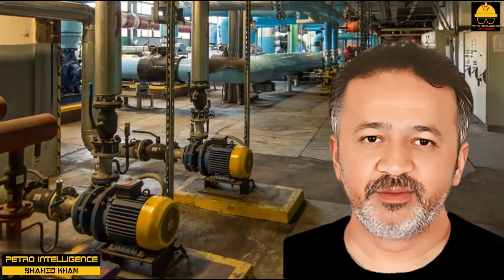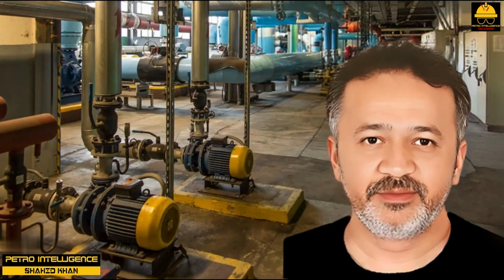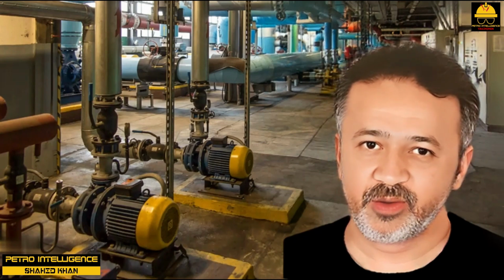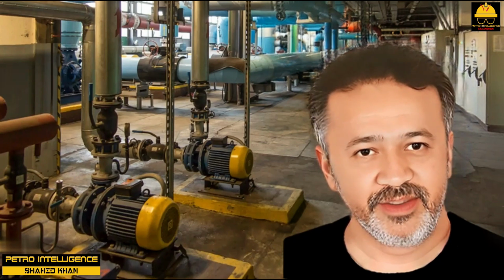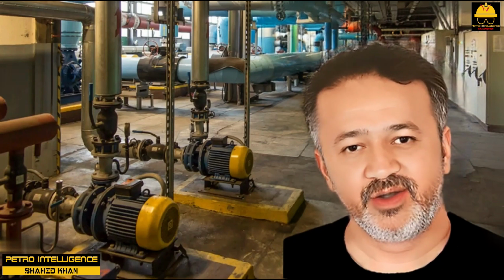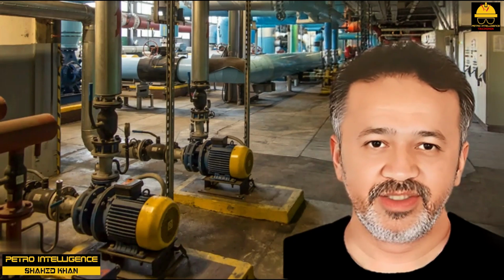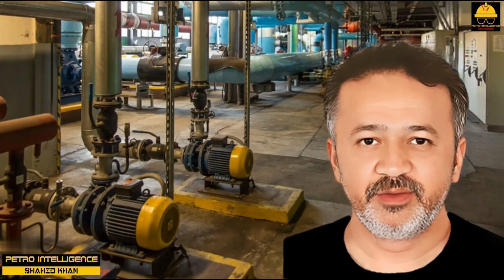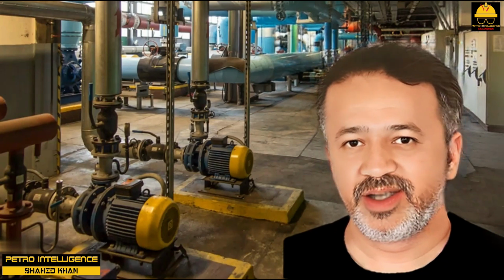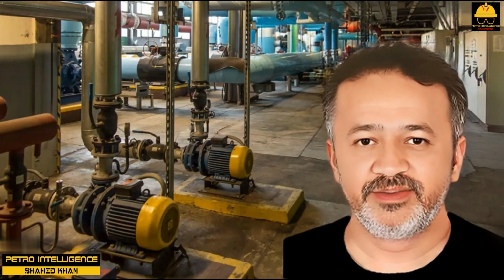Whenever we start a pump, the starting torque required to get the pump spinning requires a surge of motor amps. To avoid tripping off the motor on high amps, there is a time delay built into the trip mechanism. This delay permits the amperage load to greatly exceed the FLA point for up to 15 to 30 seconds. This is too brief a period in which to overheat the motor.